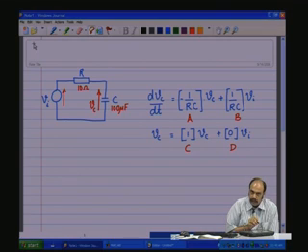You should note that the system is the same, the circuit is the same, the parameters are the same, the circuit and the system is existing only in the time domain. However, you can view it in these three major domains, that is the time domain, the frequency domain, and the PZ or the pole zero domain, to get many other characteristic information about the circuit, which will help you in tuning the circuits, designing the circuits much better.